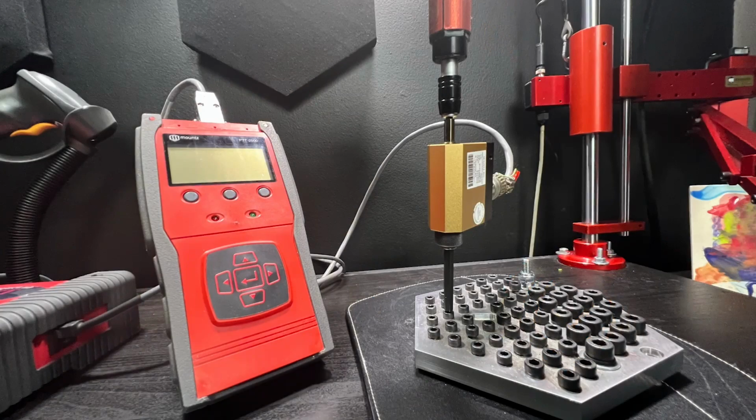And so that can be done with the use of an analyzer like this and a rotary type of sensor. This allows us to put that sensor in between our tool and our part, and we can go ahead and use the tool on our part and still capture the readings that are going on for that. So we can verify that that tool is still within its specification. And so that range or frequency can be determined by how important that particular application may be. Is it something that you do once a month that you do the check, or is it once a week, or is it once a shift? It just depends on the criticalness of that particular joint.